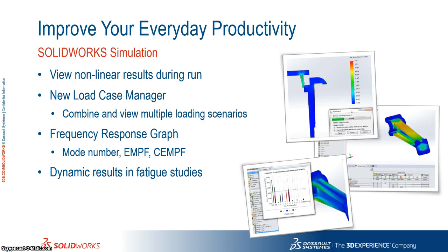My SOLIDWORKS is completely set up to default settings as if I just installed it yesterday, just with some templates added in, and I have all these parts loaded on my machine. So I'm going to show you this first. We're then going to go on to the new load case manager, which is just a really simple way to now check out all your loads and the cases and how they're managed. We've got a new frequency response graph. We can now control that with mode number, an EMPF or CEMPF. We also have dynamic results in fatigue studies. So we're going to look at all these things and then we'll come back and look at the rest of the new things in SOLIDWORKS simulation.